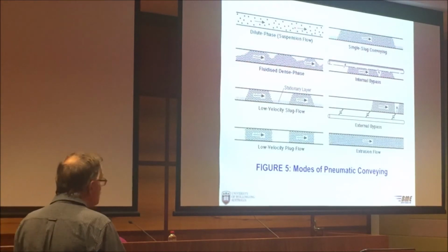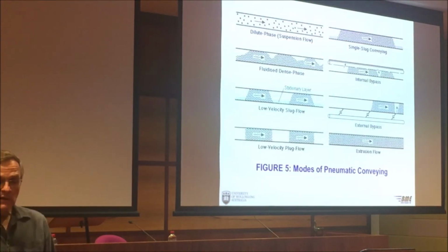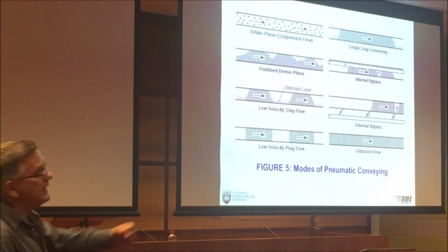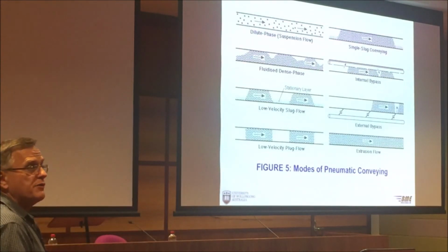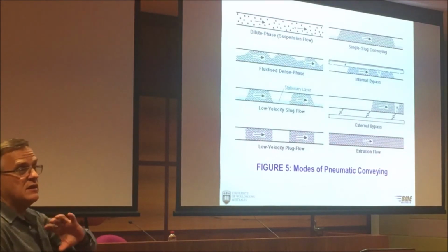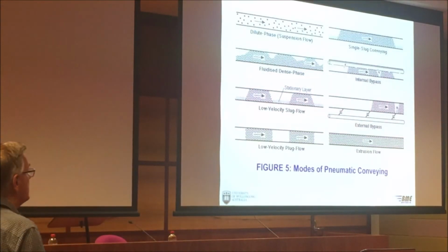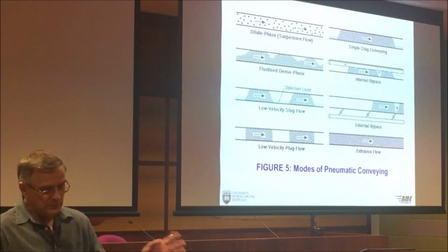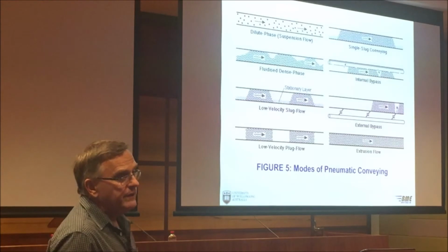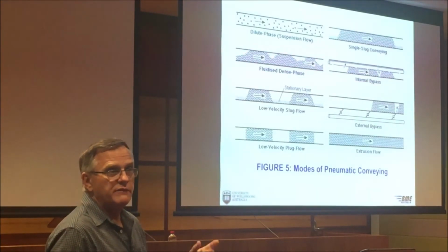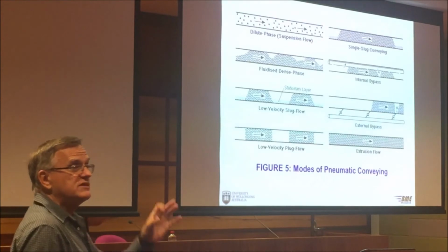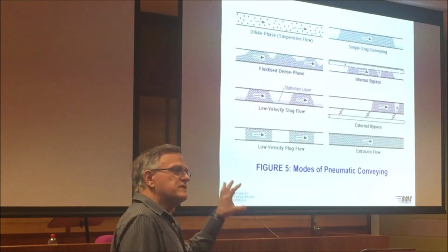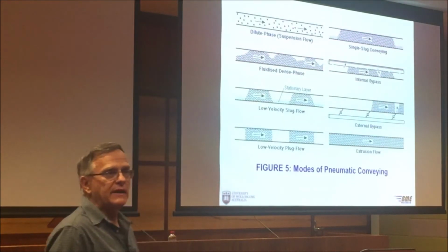And then extrusion flow is a fairly specific application where your product may be a bit wet, and you fill up the whole product and you're pneumatically pumping it basically through, the Americans call this salami flow, and the whole thing just comes out like one big sausage at the end of the day. And you can convey under very controlled conditions. We did a project for the pet food industry, conveying the dog food with gravy, the meat lumps, and also for cats' whiskers, the fish chunks in gravy we conveyed like this. Very specific application, was more pneumatic pumping than pneumatic conveying.